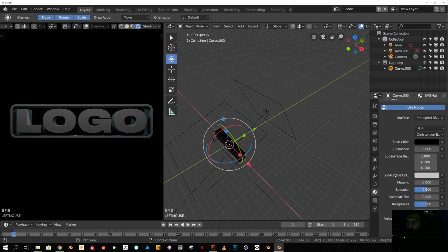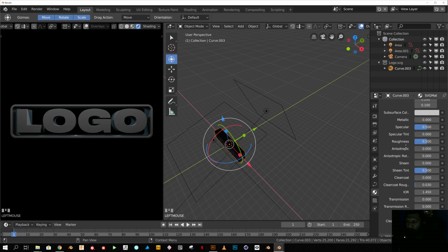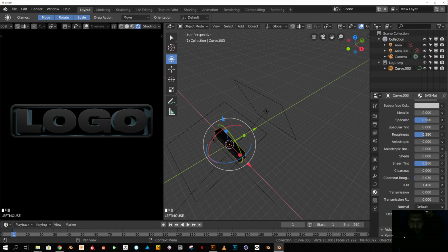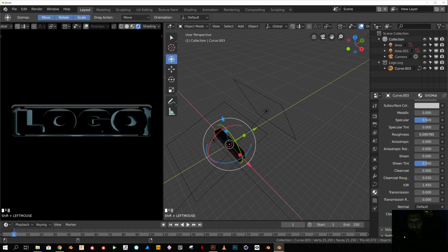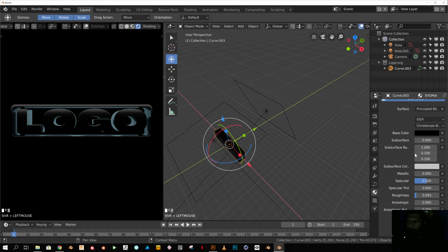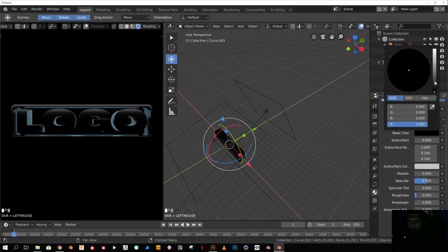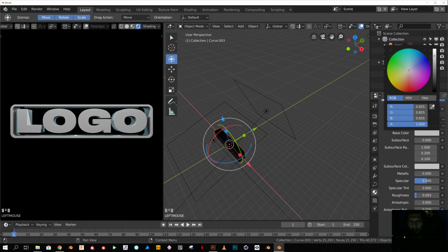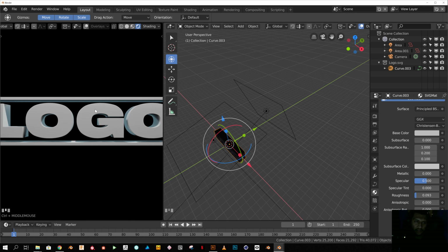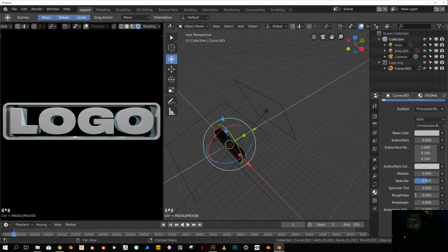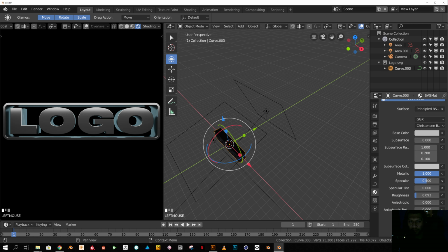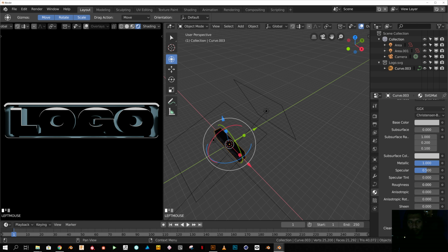Here this is the principled shader, which has most of the material properties that you need for basic materials. So I'll just decrease the roughness, so I'll just have a more shiny look, maybe just a little bit of roughness. That's looking quite nice. And then I'm gonna change the base color. I don't know, maybe to something white. This also looks quite nice. You can also just add metallic if you would like, if you are going for a more chrome look.